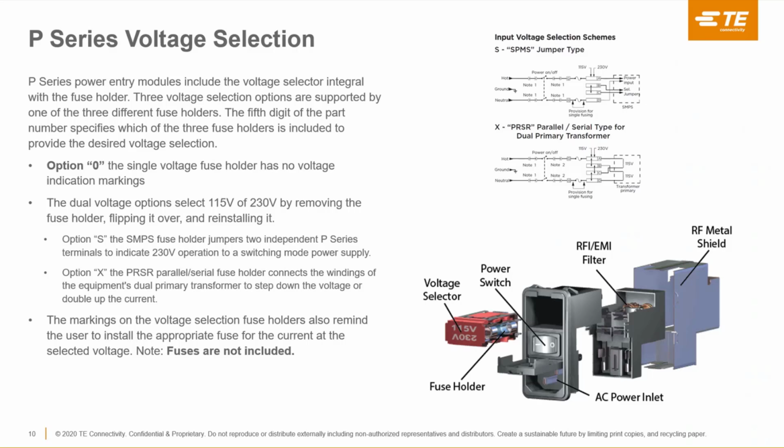The one below it was back when you used linear power supplies, and you actually had a primary on your transformer, which you had 2 primaries where you put them in either series or parallel in order to change the voltage drop from being, let's say, from 115 to whatever, let's say 12 volts. And when you wanted to operate at 230, you wanted the 2 primaries in series so that you had a greater amount of windings on the primary going down to, let's say, 4 turns on the secondary to give a bigger voltage drop. And that's what we allowed. Once again, these were designed years ago, and people get a little confused because a lot of times they don't need to really worry about that.